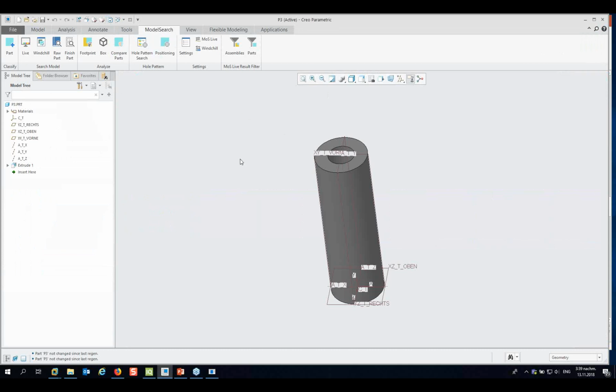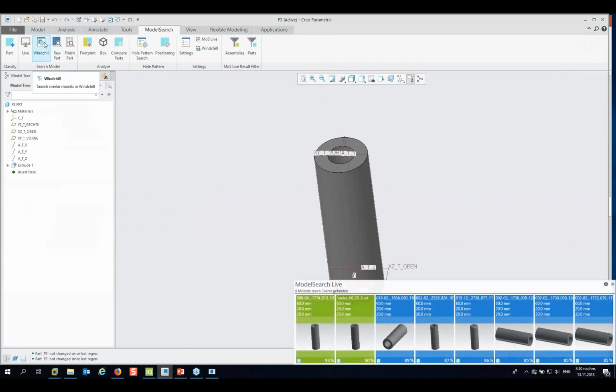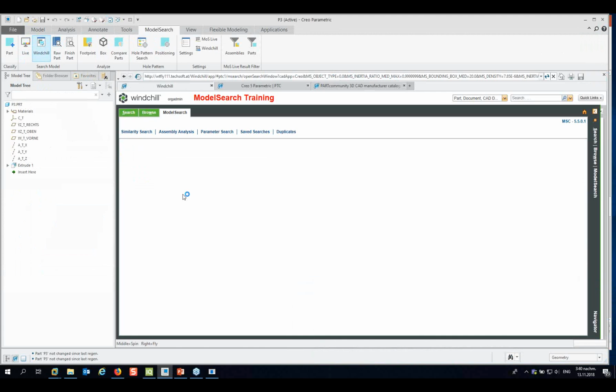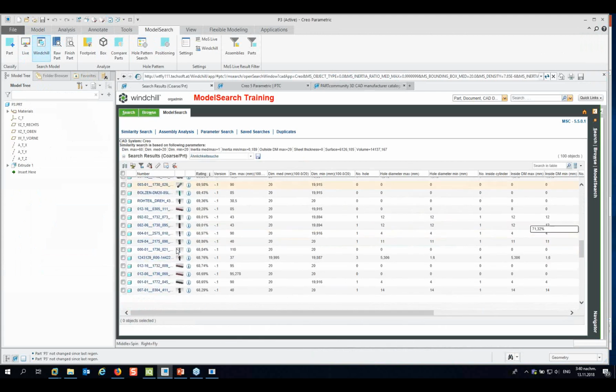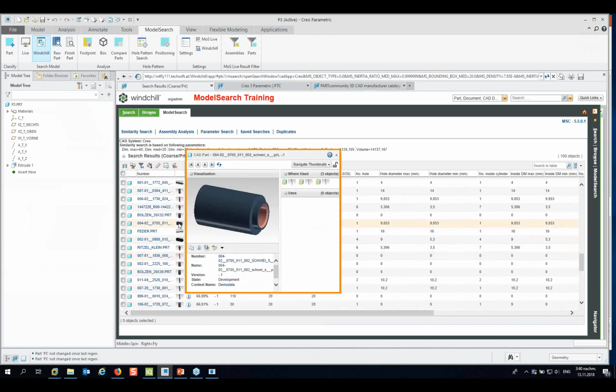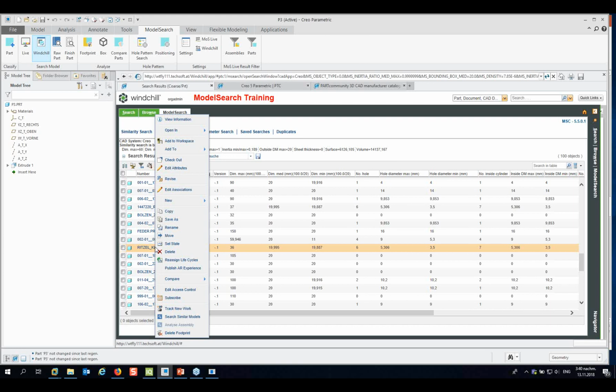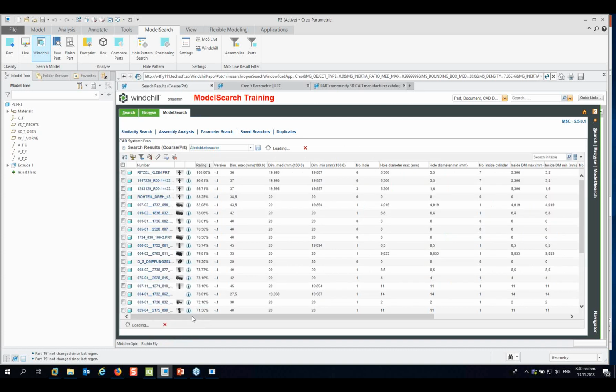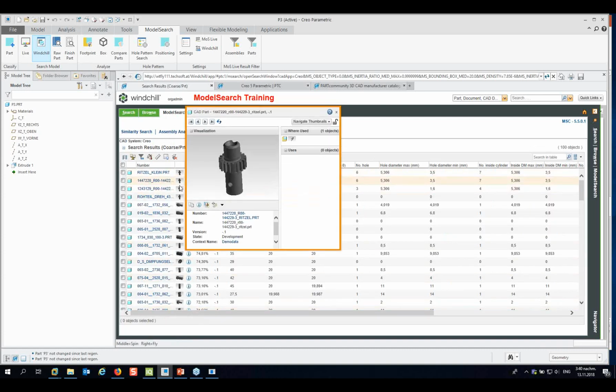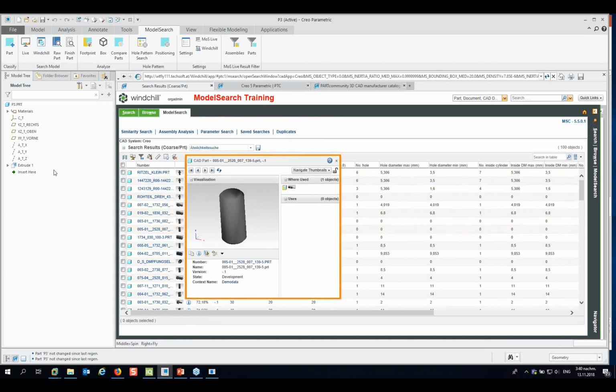So it's very important, for instance, if we use the result list from the similarity search here. Once more, if we find parts here in Windchill, this is the result here. I go a little bit further down here, and you will see, for instance, this part, this one, maybe this part. And if I say here, okay, I want to have information about similar models here inside Windchill, you will see the result here. It's always from exactly the model you select here.